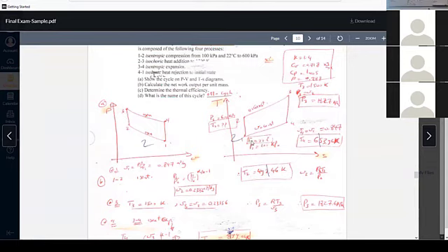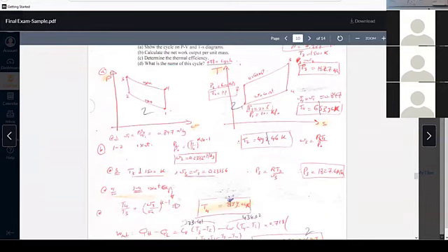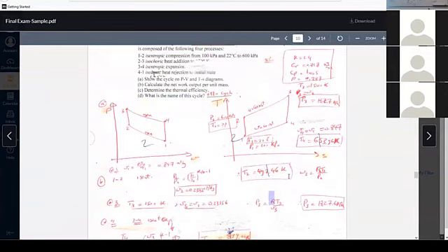Once you have all the temperatures with the isentropic, ideal gas plus something. So here you have ideal gas, P1, you can get V1. From 1 to 2, isentropic, apply the isentropic relation. You have P2, you have T1, P1, you can get T2 through the isentropic relation. T2 and P2, you can get V2, ideal gas law. Always ideal gas law plus something. At 3, you have T3, yes. You have constant volume. So get V2, give it to V3. Perfect. So from T3 and V3, you can get P3, ideal gas law.